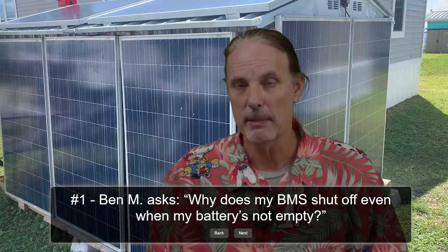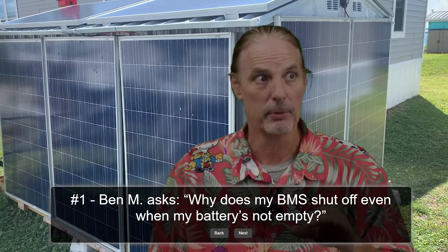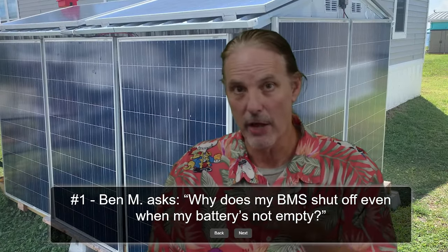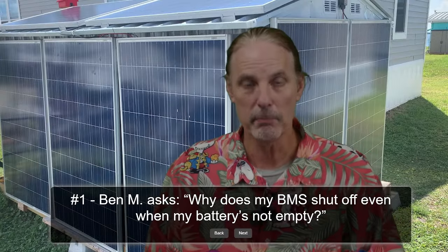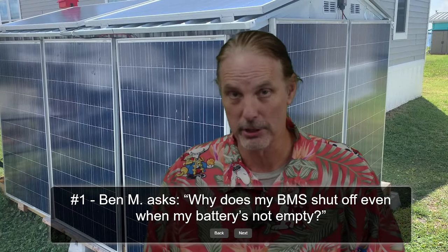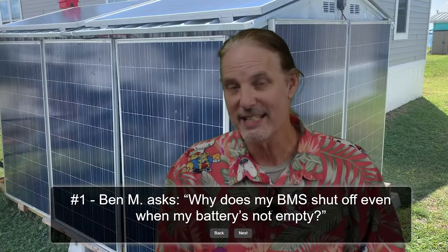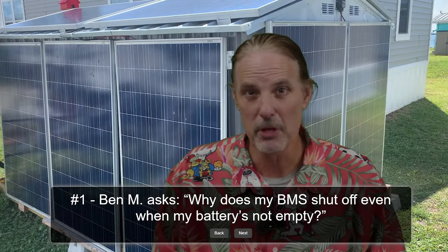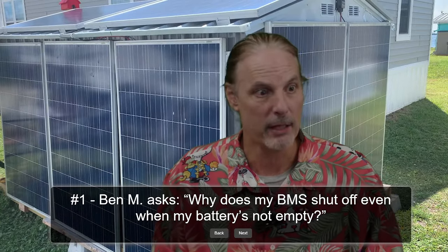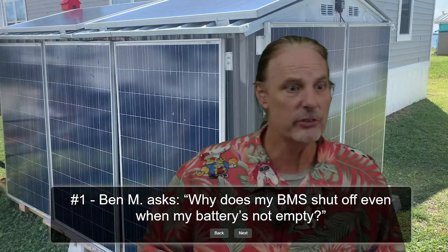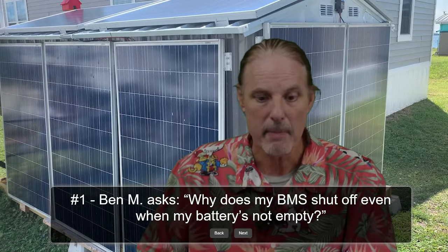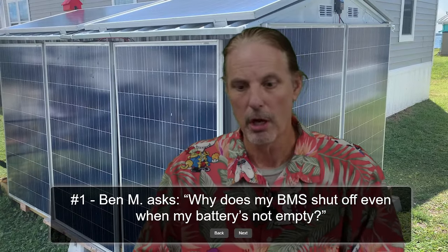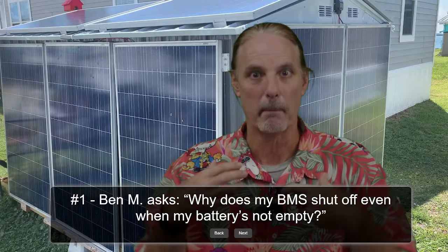Now, my JK BMS had exactly the opposite problem when it first started. It was completely and totally whacked out in the other direction, and it would show that it had 10% left when actually it had about 40% left. After a calibration, it now shows about 5% more than it should, but that's after 2 months of running off-grid and not being rebalanced. So that is why the BMS is shutting off before it is empty. This is the root of all of the BMS problems here.